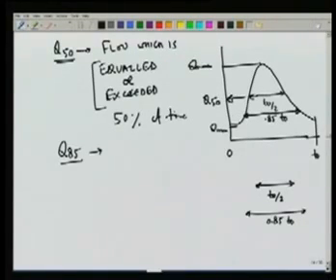So this is an important parameter. Sometimes when we are creating a facility for power generation, typically we take this 85% dependable discharge as our design discharge. So that means at least 85% of the time that much flow will be available to us.